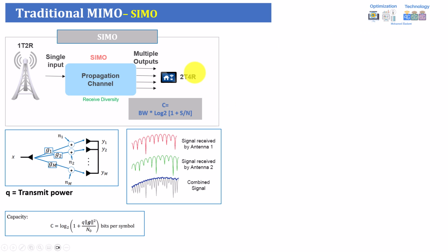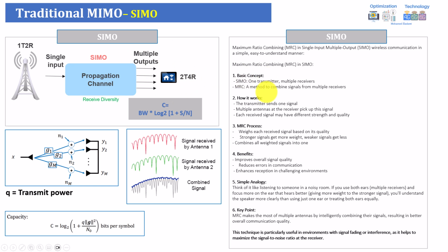Now let's jump into the MISO part to explain the main differences. But one thing to highlight in the receiver: he understands very well what the propagation channel is for each of those, because the receiver, or the UE, can measure the DMRS, for example, or the CSRS, cell specific reference signal, and he can estimate each of those antennas. So the propagation channel is very well known to the UE. This is one very important piece of information, because this will explain the difference in the next slide. So now let's move to the next part about the MISO.